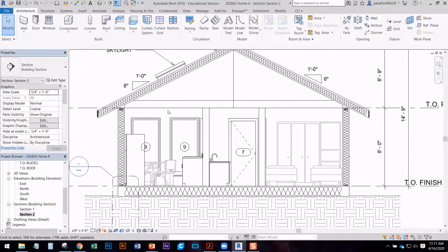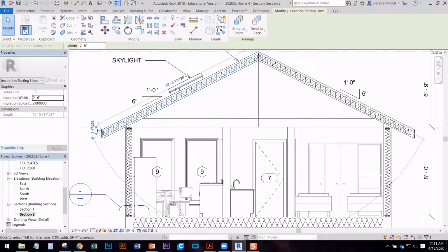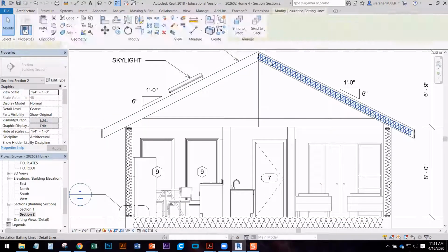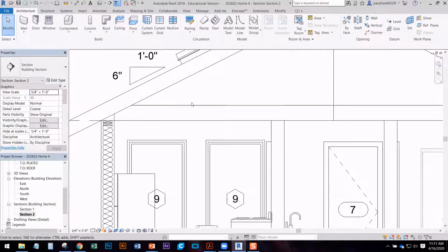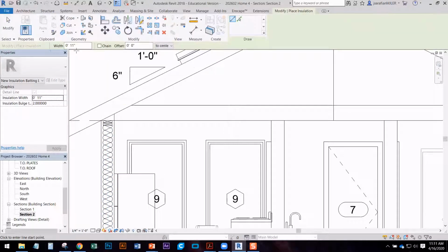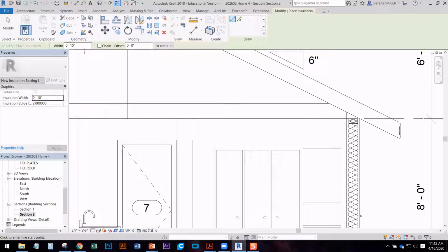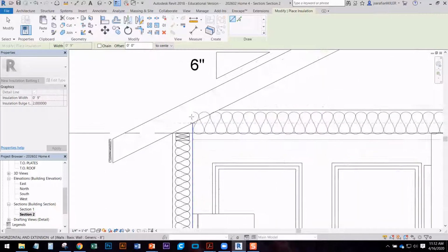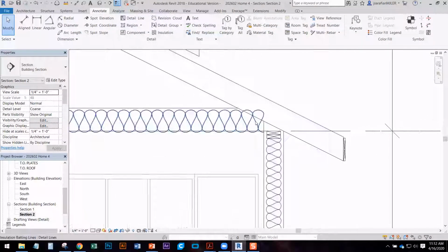All right, so walls are stopping here, and we can add insulation above the ceiling. In this scenario, our conditioned space is now just our spaces here. So we're going to delete the insulation up here, and we can show insulation above the ceiling. We have our ceiling joist, and we're going to fit insulation into that. So I can go to Annotate, Insulation, and we'll do 10 inches. Too big. We'll say 9 inches. This will extend. We want to create a thermal envelope, so fully insulated.